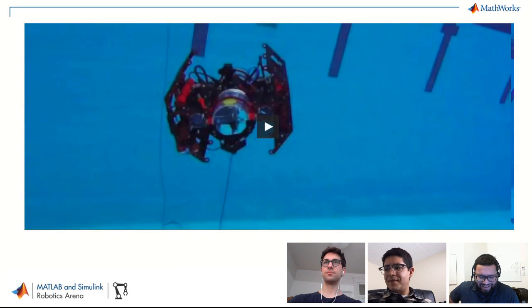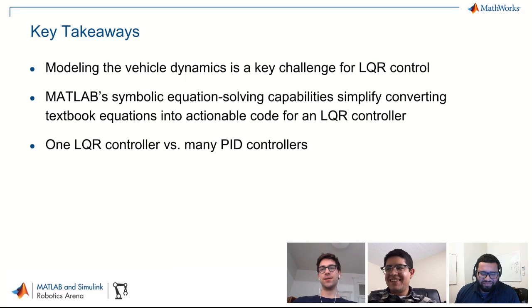Okay, awesome. So I guess the key takeaway here is that LQR is kind of a plug and play thing, but the hard part is getting the vehicle dynamics, and that's really what's going to determine your success here. MATLAB really did help us a lot with that. The symbolic equations and MATLAB in the loop were really helpful.